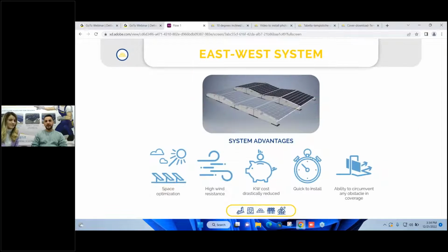Like you see in the pictures, the most chosen by our customers is the standard ballast, which you can configure in East-West, right? The East-West system, as we all know, is very common and very used. As we mentioned before, in commercial roofs, those people want to generate more power and implement more modules. You don't have a lot of space on the roof and you want to place more modules, so the orientation you go for is east-west. It could also be used whenever you have a bad orientation of the building. You want to generate more power, and you definitely go for the east-west system.